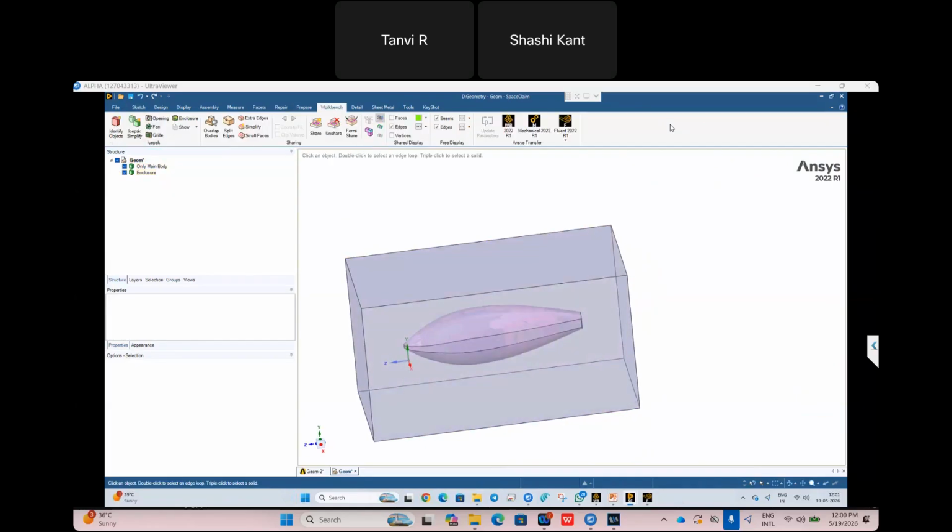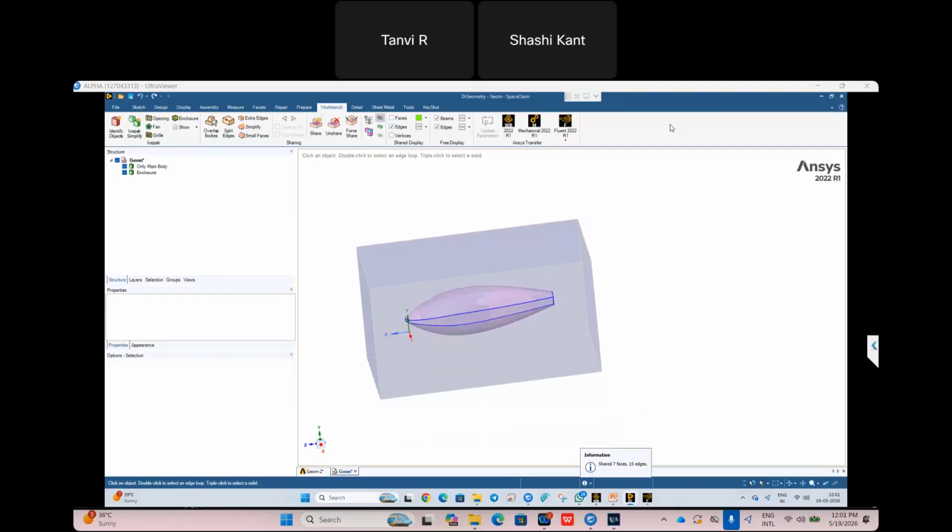We will have a shared topology to share the topology with the geometry. Shared topology means the structure we have of the eVTOL, and we have the surrounding air. So there should be an energy transformation happening in terms of the multiphysics. Once the higher pressure is generated on the eVTOL because of the aerodynamic shape, then we need to see the response of the eVTOL body or metal thickness, whatever we have.